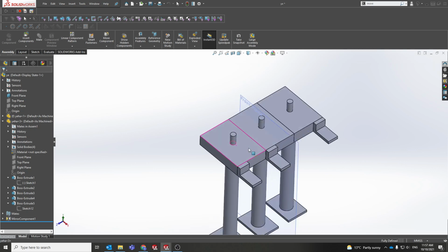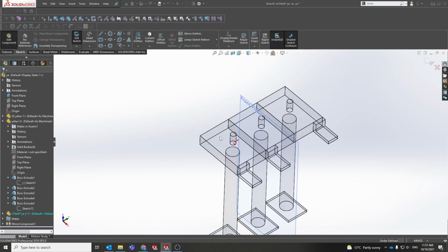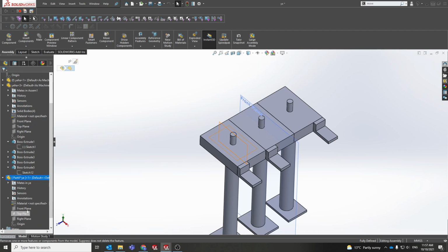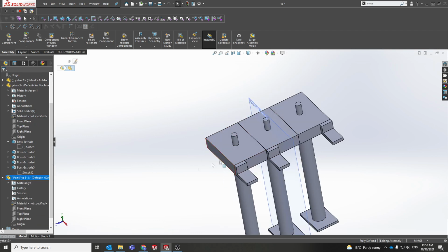Now if I wanted to create a part in the assembly, it can be done. Sometimes it doesn't work out as nicely as others. So new part, I'm going to place it on this surface here and it'll automatically put me into a sketch. Now if I don't do anything with this, if I just close it again, I can change where that sketch plane is, and this thing will probably not be defined either, so it'll just be floating still.